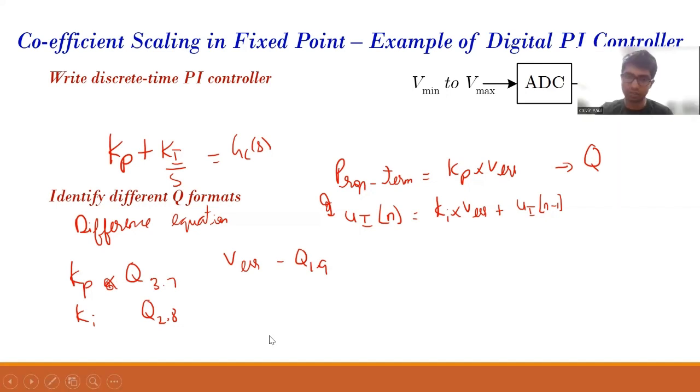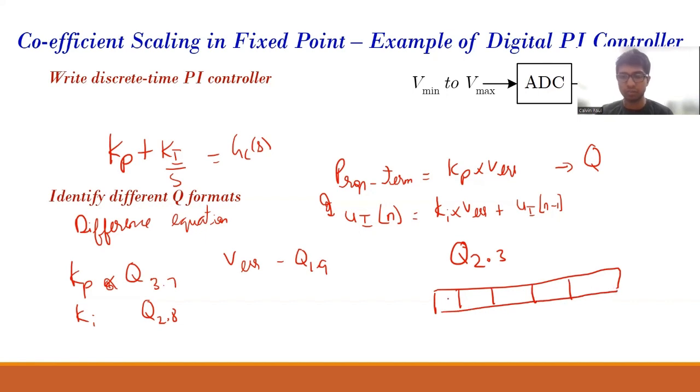So Madhu was asking something. What is the question? How signed? Okay. So this is a sign notation over here. Let us assume this number Q2.3. This 1, 2, 3, 4, 5 can be some bits. It could be 0, 1. Assume 1. This could be 0. This could be 1, 1, 1, etc. In this format, when we are told it is a sign bit, the first bit is my sign bit. And I have assumed a dot to be over here. This is just fictional, just for my understanding, not for the compiler to understand.